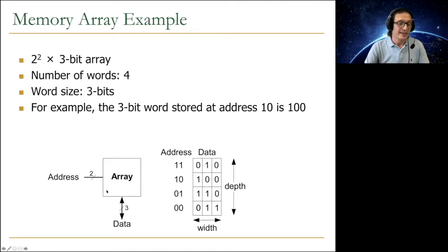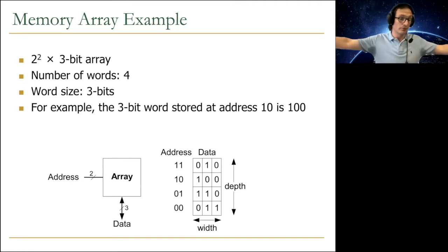Okay, so here I should say that the row size is only 3 bits, right? But your row size in DRAM, for example, can be 8 kilobytes. So you may, for example, have a number of rows, 16,000 rows, and 8 kilobyte row size in each row. But your data out may still be only 64 bits, for example. You may get only 64 bits out of that 8 kilobyte row, or 64 bytes out of that 8 kilobyte row. Basically, you select or you multiplex the data, the column that you want out of that memory.